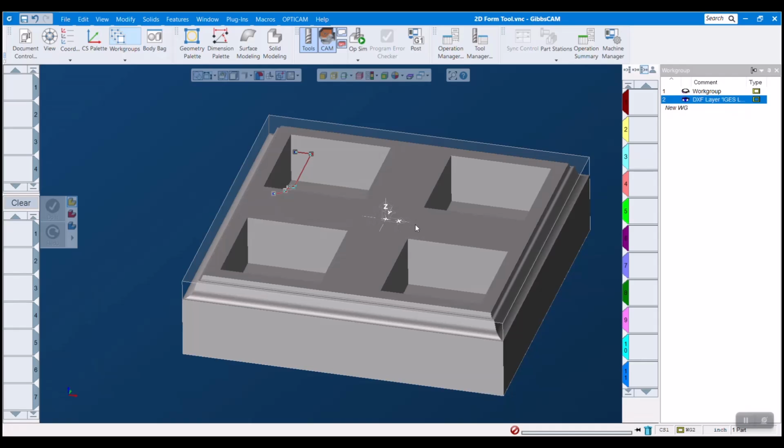I think when you import things from drawing files, they typically come in the XY plane, so this isn't too much of an issue. However, it is still necessary for this to work. The second rule is the tip of our tool here must be at 0, 0, 0 of our original coordinate system. So how we do that is we just double click this to chain select it, and we can go